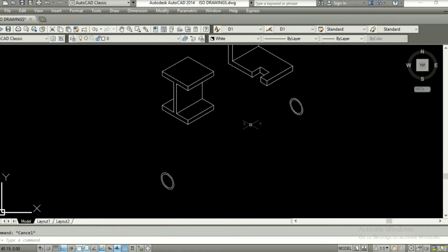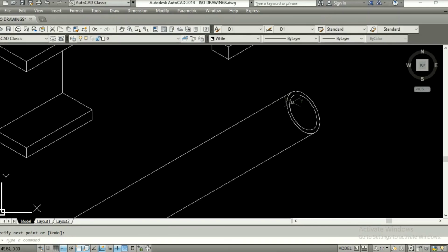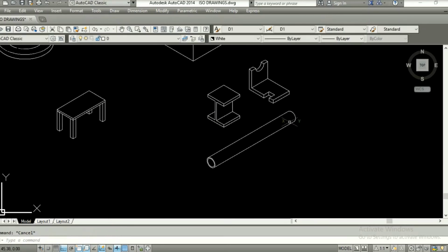Yeah. Now join line, quadrant to quadrant. Quadrant. If you don't find quadrant, just type quadrant. There you are. So again, quadrant, QUA, and quadrant. Yeah. Delete the inner stuff and trim the outer stuff. Trim, cross. Cross helps you to identify the objects where the cursor moves. Okay, now this is done.